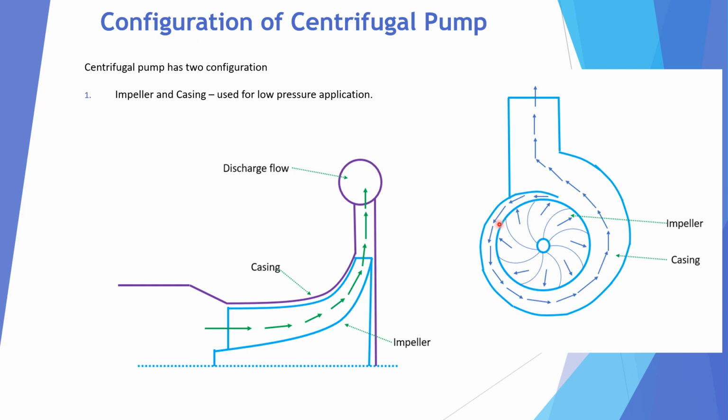So if the flow is in this direction, the fluid is adding up. So the fluid which is coming here, all are adding up. So the mass of the fluid starts increasing. That is why the shape is a spiral having increasing area, to have constant velocity.